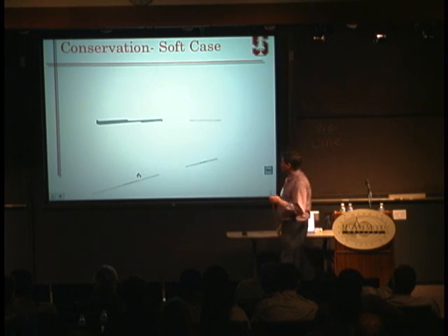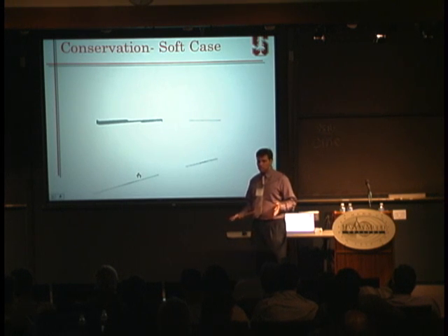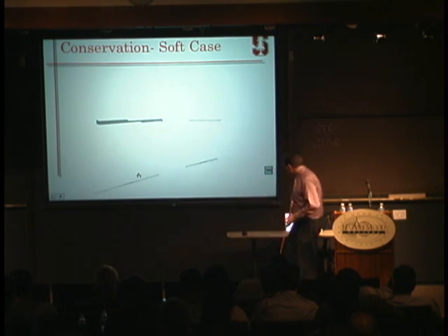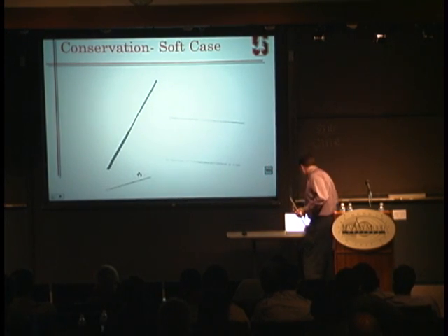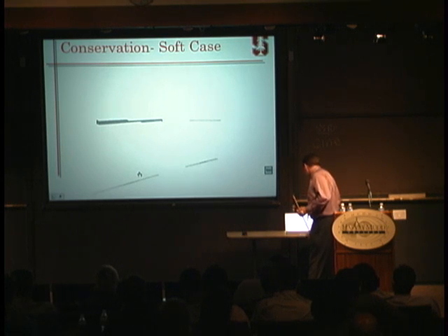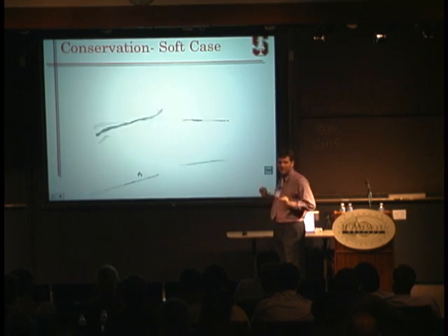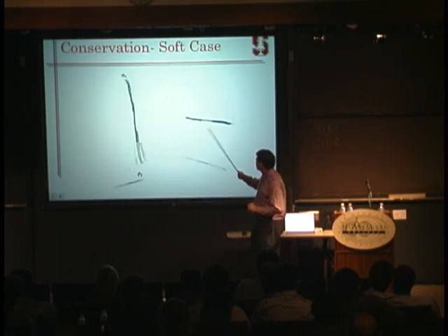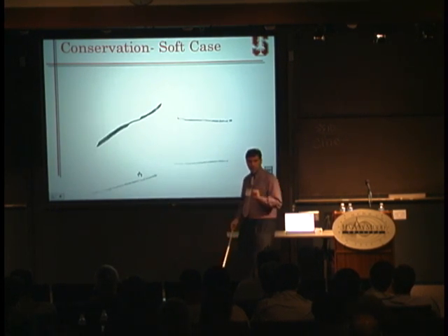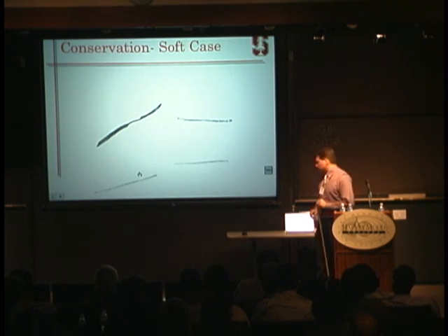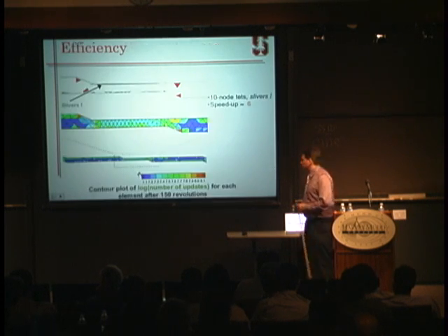Well, but this case is kind of boring because it's too rigid. So we just soften the material. We want to do large deformations now. This is not a realistic thing. You will not fly with this. But, you know, it's nice to see what it does. So this flying spaghetti is rotating, but still you preserve the location of the center of your blade, and you rotate always in the same plane. And you will see that the energy is perfectly well preserved as well. So this is not unstable numerically, it's just mechanically unstable, if you want.